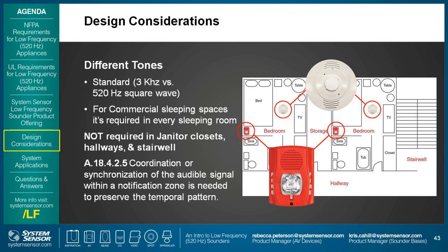The requirements are only for sleeping spaces and not intended throughout the building. When people are awake and moving about, going about their business, the standard 3 kilohertz product is a very effective way of alerting people, so they don't really need the low frequency in those places.